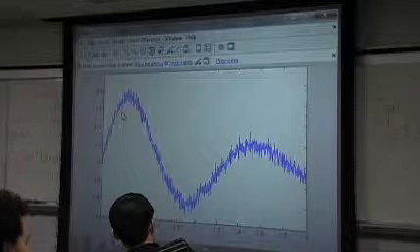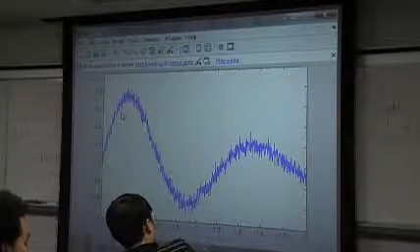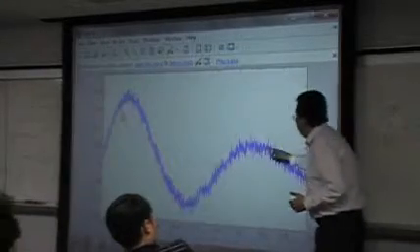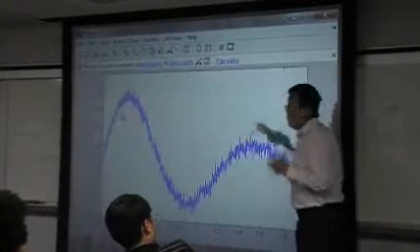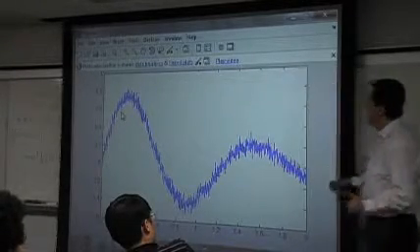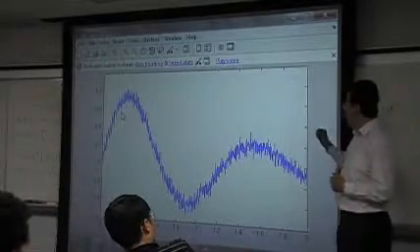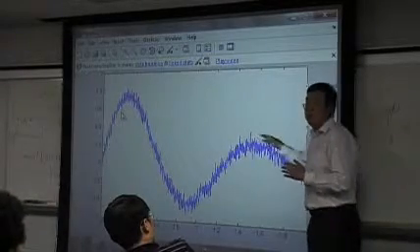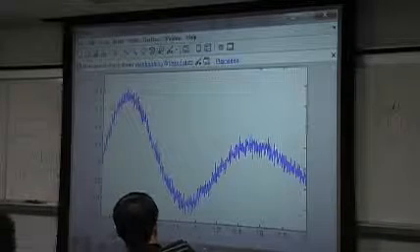So if you are trying to use a PID controller, you may not use it directly. Because the real signal may be very smooth, however, the signal may have a jump here. If you take the derivative of it, it might be very dangerous. So in real applications, we cannot use a PID controller on it directly. The better way is to filter the signal to make it smoother, and then use the PID controller to do it.